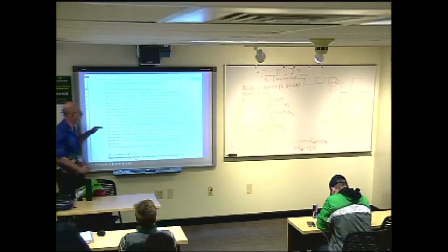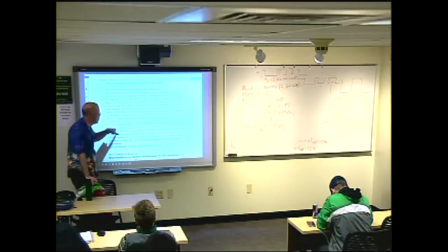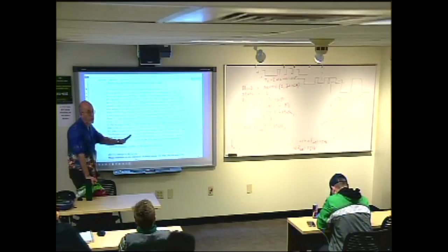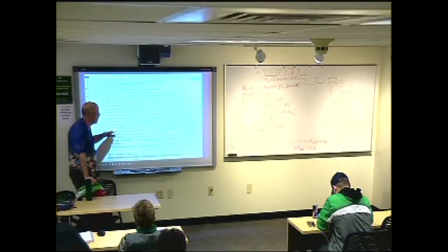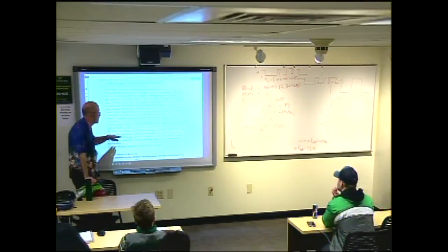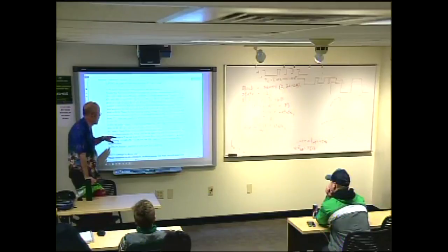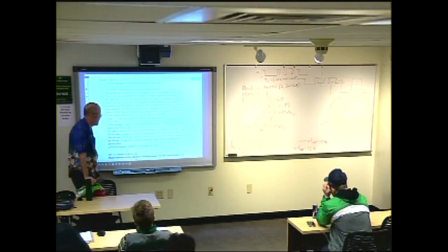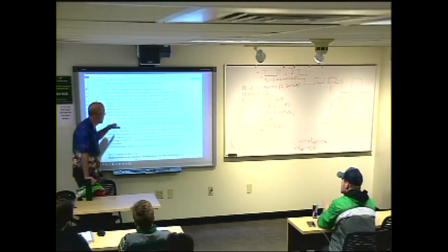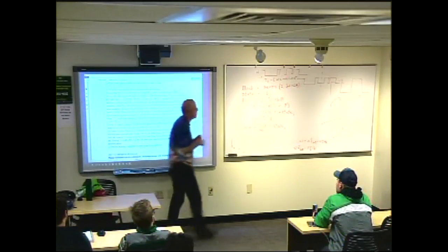Now what we want to do is assume a noiseless system here in part A, and I want you to run it through your bandpass filter with no noise. I just want you to see what your filter does to these on-off pulses of voltage coming through, okay? I want you to create, just as you did before, a 3-level flicker noise system, the same magnitude you had before, with the same expected state change time, okay? And so now we're not doing 5 milliseconds anymore, we're doing 20 microseconds.